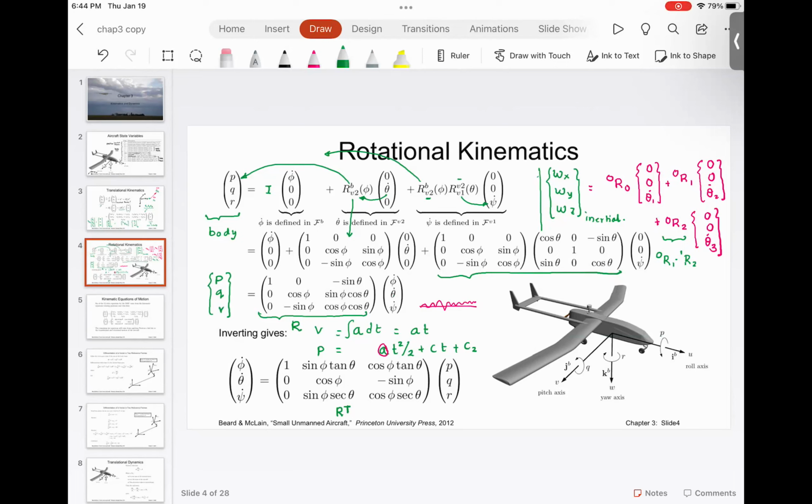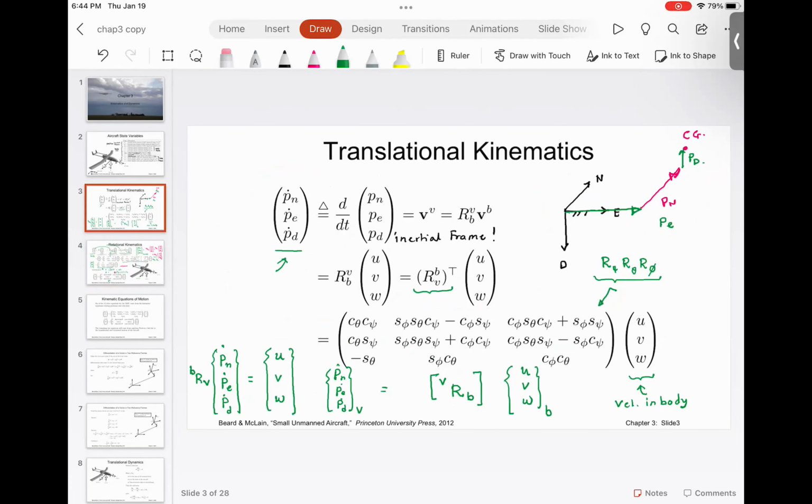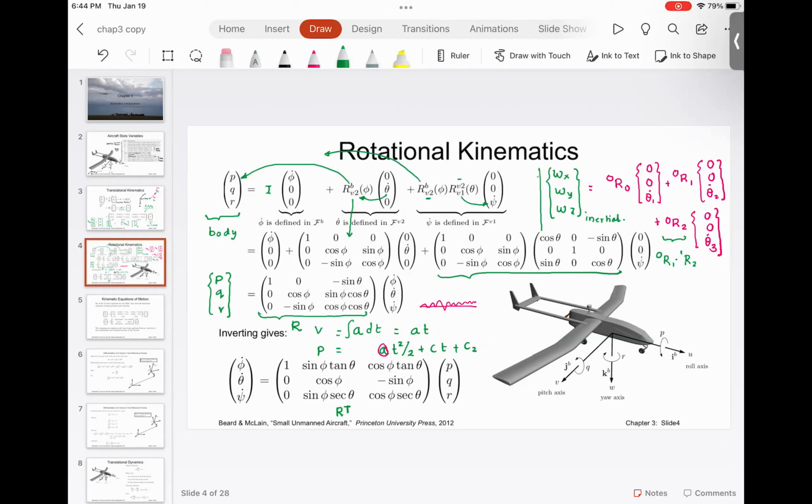So the two important set of equations that describe the aircraft kinematics are this first equation that we have shown over here and the second equation that we derived over here. So these 6 equations give you the rotation transformation and the kinematics equation. Here is something else that I want to talk about. How do you solve these 6 equations?